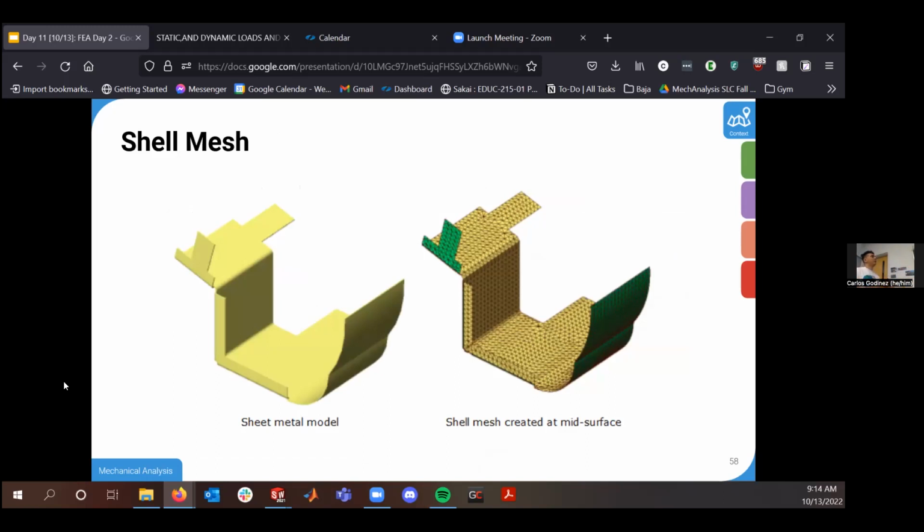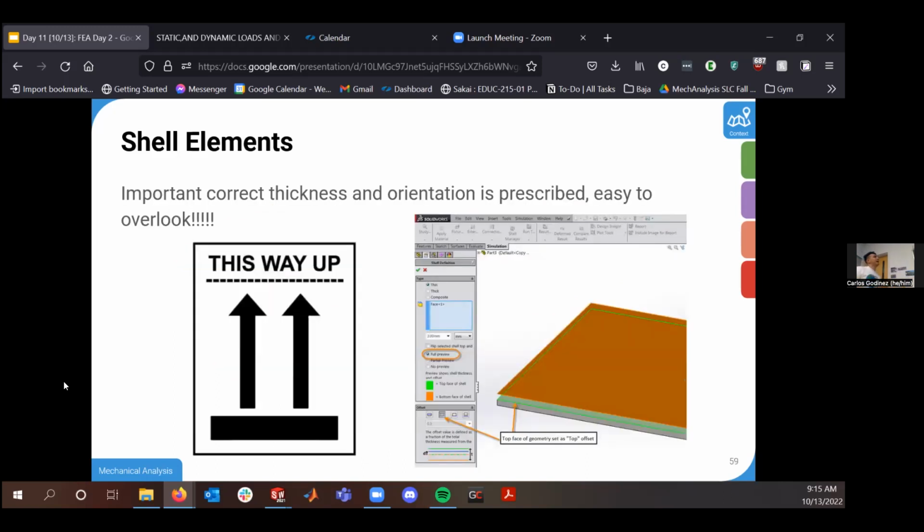When you do shell elements, it gives you the top of the model and the bottom of the model. It'll make a guess for it, depending on your global coordinate system, and if it's incorrect, all elements will have the ability, within the screenshot, there's flip sides for which way is up, which way is down. If you guys find a reason for it, I'd be very impressed and would love to hear more about why it matters outside of an orthotropic case study. But it is important to remember in all the places that tell you to do that.